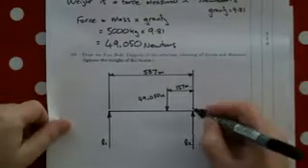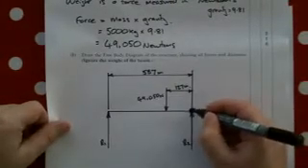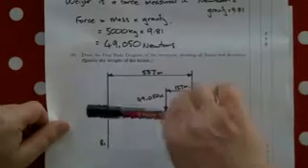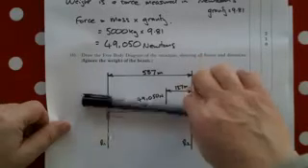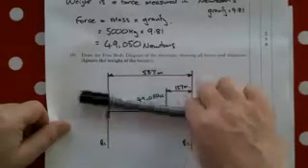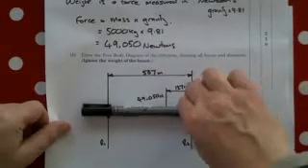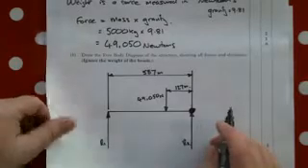It says calculate by taking the moments around R2 the size of reaction R1. Right, this is not as difficult as it sounds. What we do is we imagine R2 is now a pivot point, so it's something that everything can rotate around. Okay, so the weight of the container would react in this direction, and the weight of R1 would react in this direction, and this is the clockwise and anti-clockwise moments generated by these two forces.